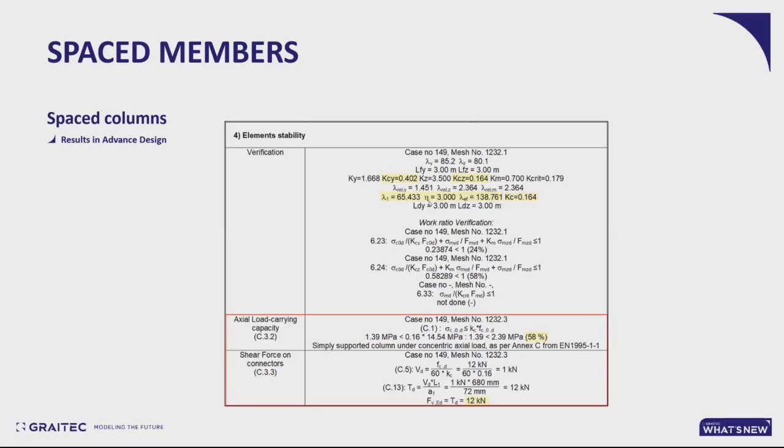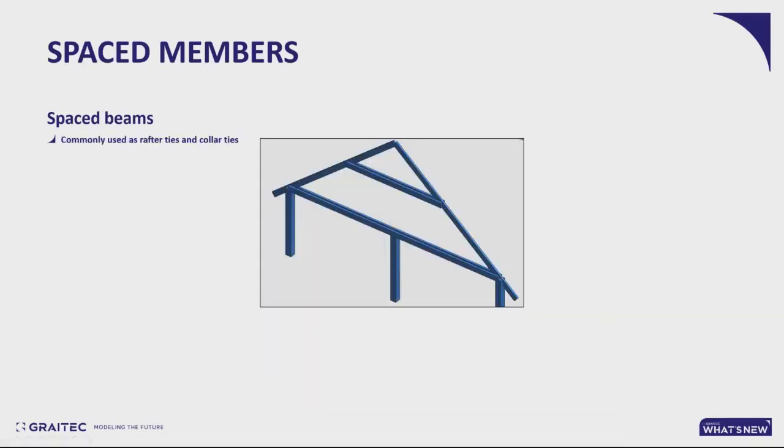And also we've got the connector types, which in turn gives us an effective slenderness and a very small buckling coefficient that is actually driving the design and giving us the utilization for the actual load carrying capacity verification. And then we've got the shear force to properly design the connectors, with the distribution formula being the one for the two-shaft configuration.